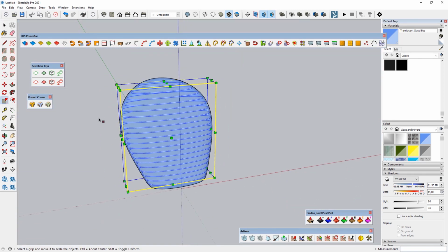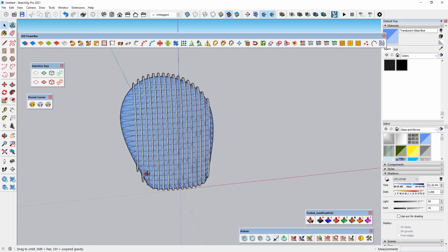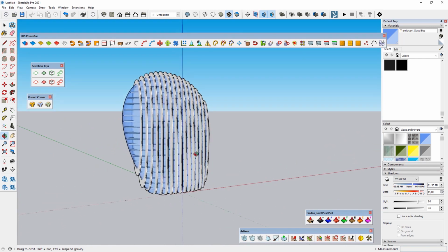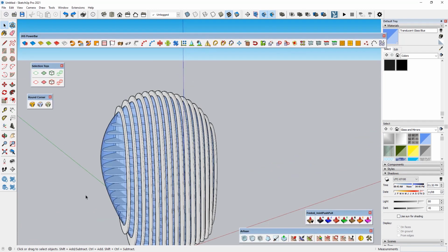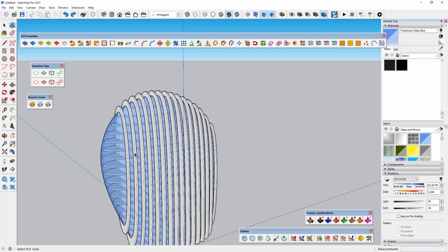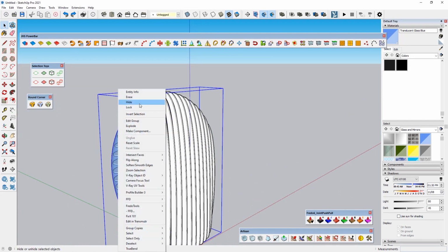So now it should be okay, and if we unhide the outside rings, you will also notice that we need to remove the surface that is inside, and this is also easy to do because we need to select all the rings at the same time, and with the solid tool we need to choose the split, and we need to select the glass. And after that there will be some calculation, and as a result we will be able to remove the inside surface.